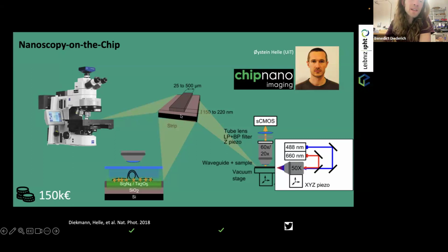And then what's happening if you couple light into that, since it's an optical clear waveguide, so to say, is that you have light transported through this little chamber or chip here, or channel, it's better. And then this evanescent field, what we were talking about last time, this field that's kind of lurking outside the waveguide is eventually being absorbed by the fluorophores and then also excites the fluorophores.